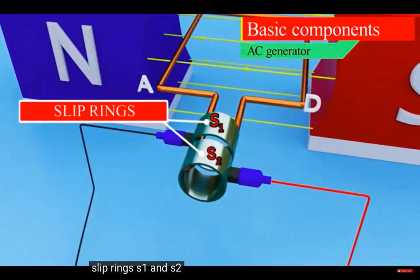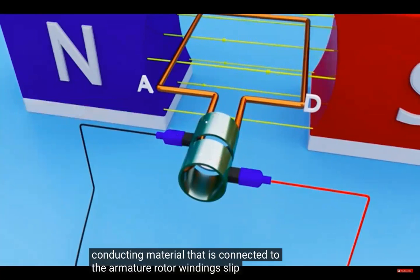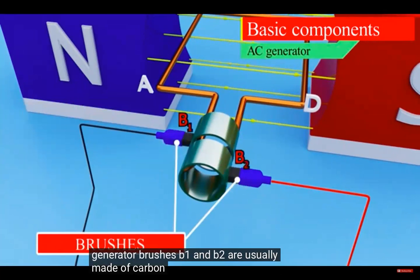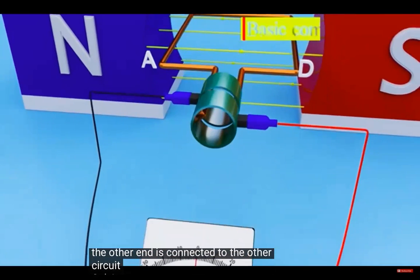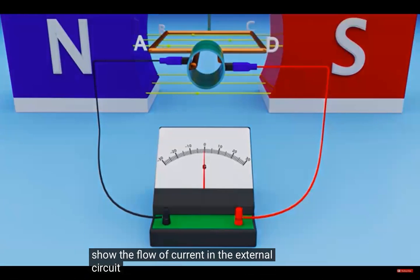Slip rings S1 and S2 are connected to the armature and rotate together with it. The slip ring consists of a circular conducting material that is connected to the armature rotor windings. Slip rings are used to bridge, transfer, and carry the power to and from the rotor of an AC generator. Brushes B1 and B2 are usually made of carbon. One end of each brush is in contact with rotating slip ring and the other end is connected to the other circuit. Galvanometer is connected to outer circuit. Purpose of galvanometer is to show the flow of current in the external circuit.